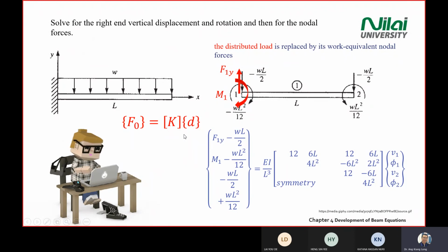So what you have is just transferred from the free body diagram that you just drew. Again, we do not consider F1x here. So F1y is positive, and you have a negative WL/2 in point 1. You just copy what you have from the diagram for the first point for the F component: F1y, negative WL divided by 2.